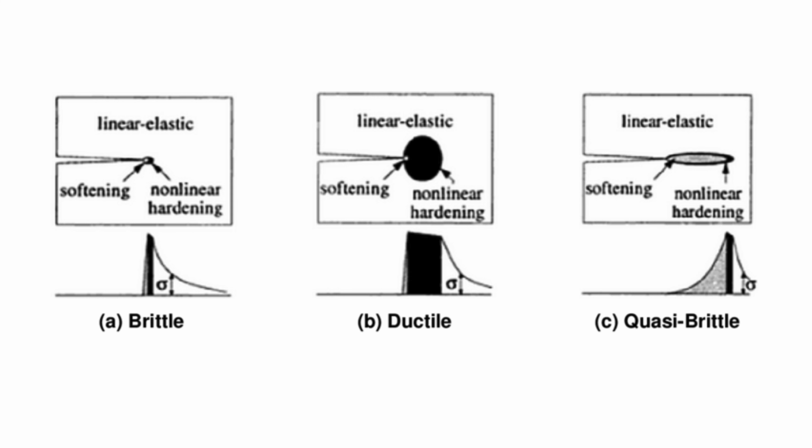The fracture behavior of polymeric materials has been extensively studied in the literature. Environmental effects, temperature and strain rate, for example, can significantly modify the emerging behavior of the material. By increasing the strain rate, a polymer can change from a viscoelastic plastic ductile to an elastic brittle behavior.